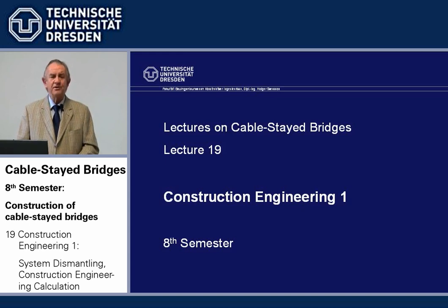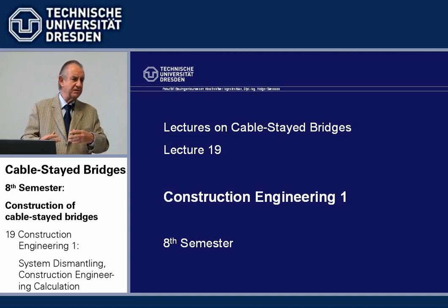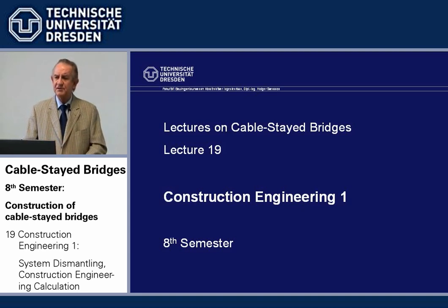An important difference to the usual calculation of the final stage, as we do for all bridges, is the highly indeterminate system of a cable-stayed bridge. You remember, in a very rough first approach, the number of statically indeterminates is equal to the number of cables, roughly.